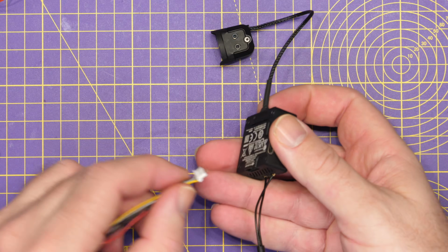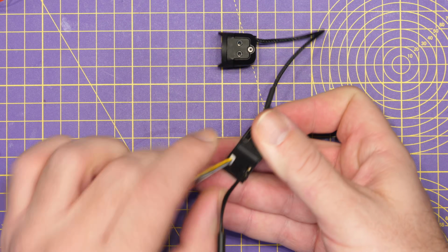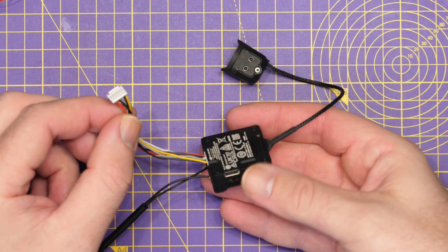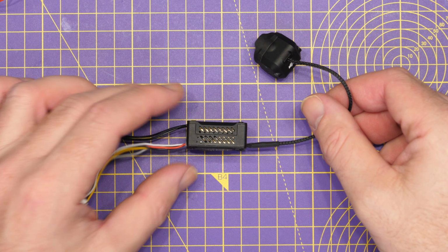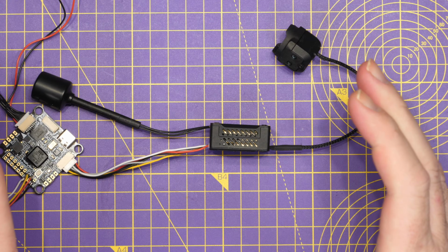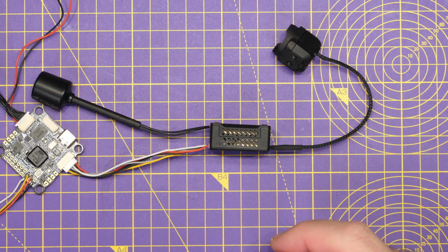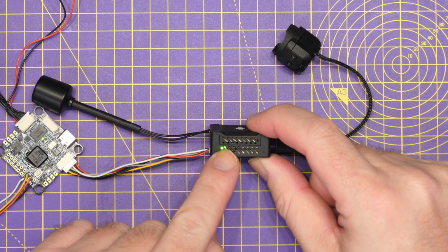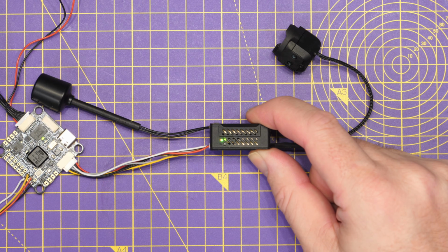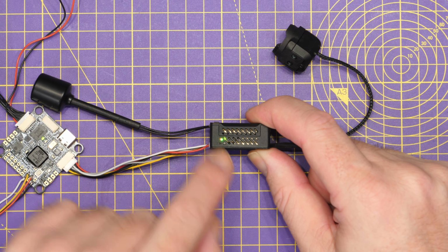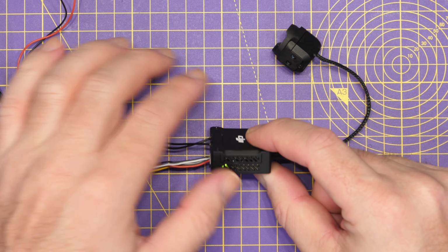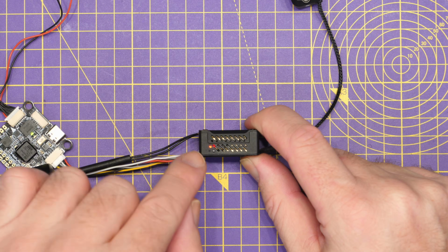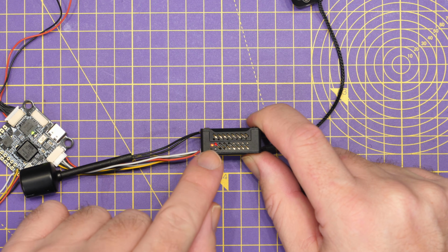That is the port that is located down here on the side of the unit, and then this needs to be wired to your flight controller or at least to your battery to be able to power the unit up. When you do have it connected, what you should see when you power it up is as follows. When it first powers on, the LED should go green. This is as the E unit is booting. This LED is located just above the bind button here on the right side of the E unit as you're looking at the DJI logo towards you, but then it will change from green to red.